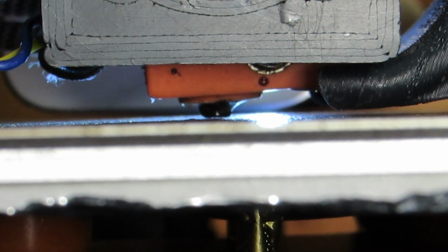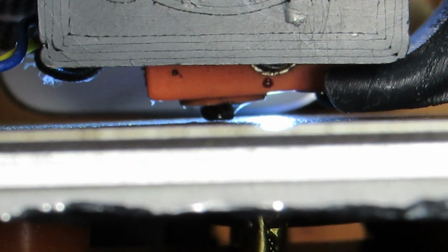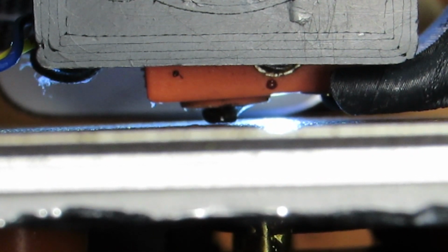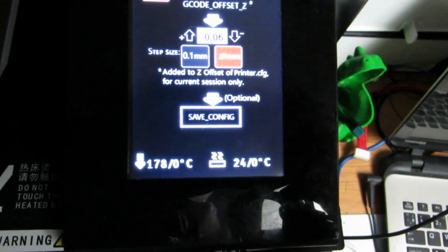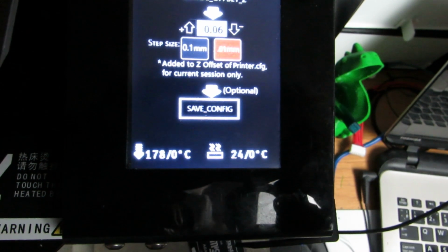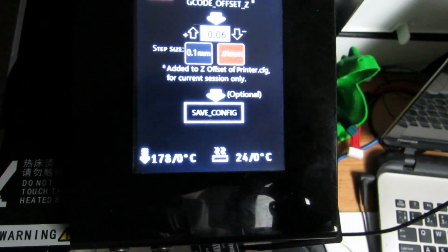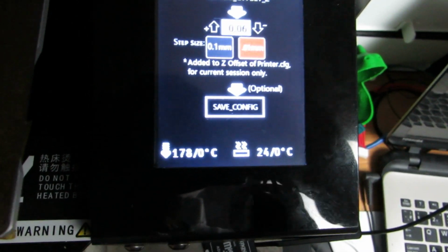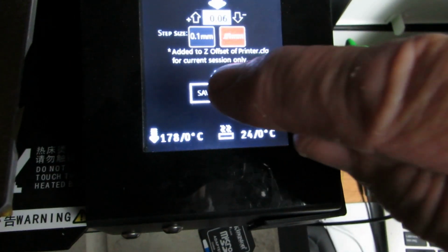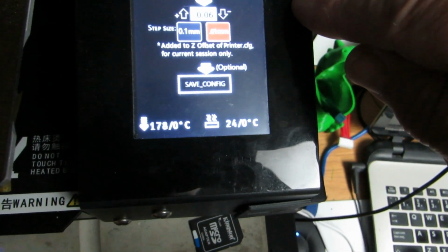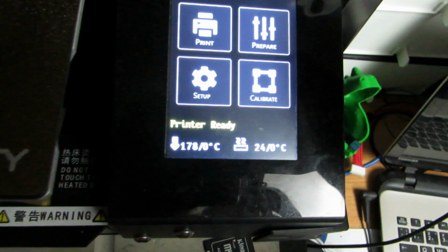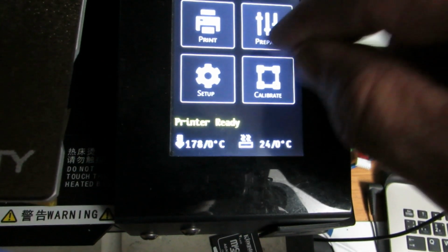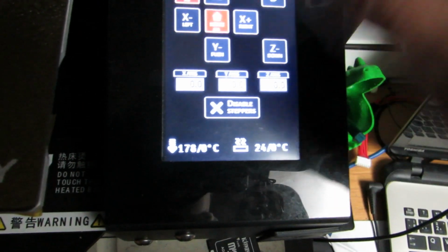That is an offset to the offset. So that is a correction factor that you can now apply to the Z Offset to make it precise for your printer. So in my case, the offset has resolved at 0.06 millimeters, which means the 0.20 default is off, and sure enough I'm back to the 0.14 that I said was optimal for my system. So to save that now and correct the offset, you press Save Config, and that will save to the printer and reset. And now my offset is the 0.14 instead of the 0.20. And I don't want to leave my bed with the nozzle pressed up against it in the center, so I want to remember to home all when I'm done.